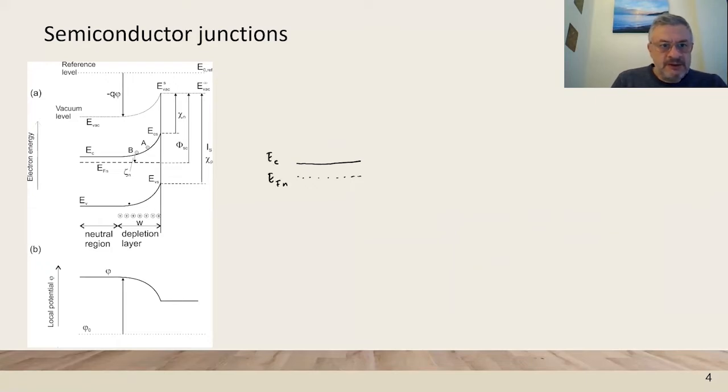But when we arrive at the surface it will be modified to be in equilibrium with the contact material, so that, for example, we can obtain band bending. And then we can see that in this region, there is a much lower concentration of electrons than in the bulk, because the conduction band is far from the Fermi level.